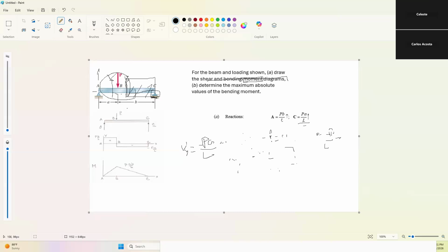So we have to use the force P, and then let's do that equation again. We don't know exactly where it is we're going to solve for. So the distance is L minus X, where X is whichever point on the beam from 0 to L. And remember, moment is distance times force. So that's the distance, and the force is the force that we already know.